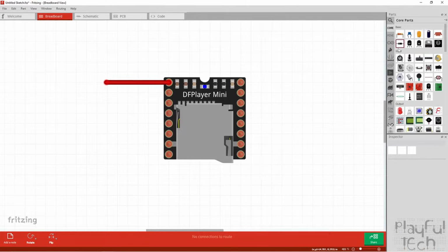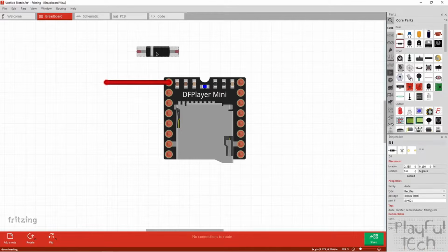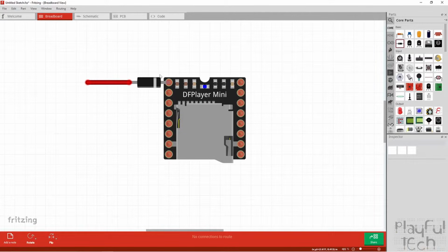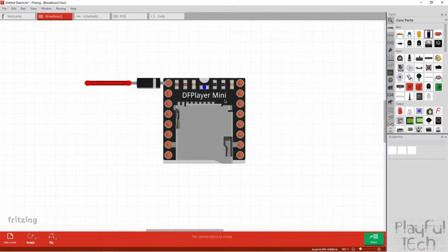And a common way to do that is to place a diode in series in that voltage line here. A diode typically drops about 0.7 or 0.8 volts across it. So you've got the voltage being supplied at the first pin here now about 4.2 volts, and that's an ideal value. Now, as well as specifying the correct voltage, you also need to make sure you can supply sufficient current.